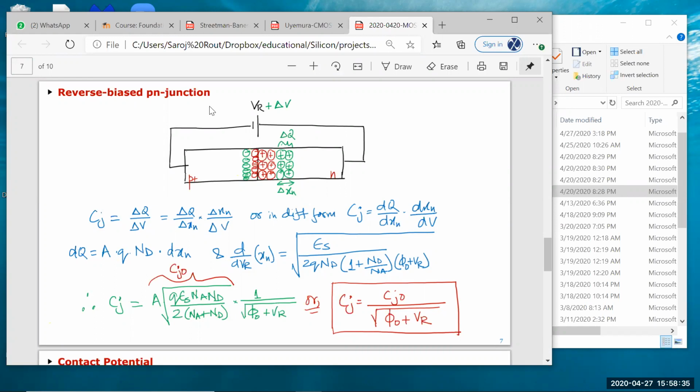Okay, and this is a crucial thing to remember, because in chip design, you basically have billions of these reverse bias diodes everywhere. Plus, your channel is actually reverse biased as well. It's a depletion, giant depletion, like we saw last time, and we'll look at it again. So it's critical to understand that.